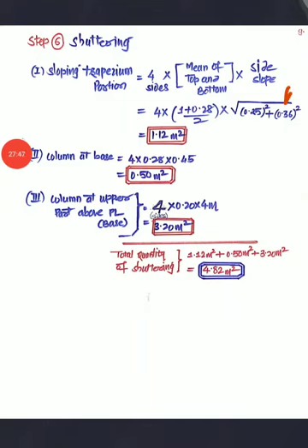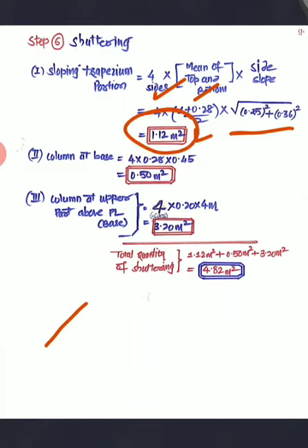That 36 I have shown here, right? So that is 4 into (1 plus 0.28) divided by 2, and square root of, because you want that inclined portion. So that is going to be 0.25 square plus 0.36 square. So it is going to be 1.12 meters square, all 4 sides, right?